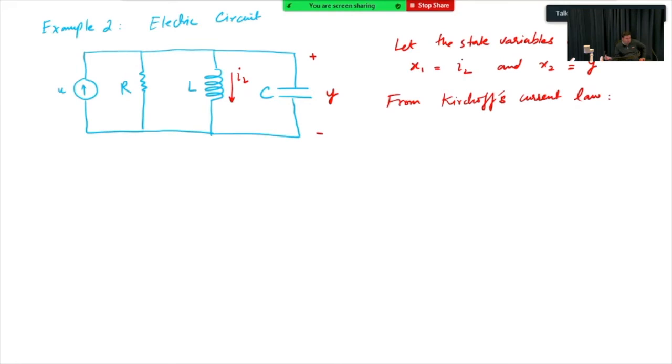So oftentimes you don't have to really bother with modeling the system. When you work with a particular system, let's say a robotic arm or a damping system, you basically know what the system model is, and oftentimes people have already developed state space representations, so you actually work with them.